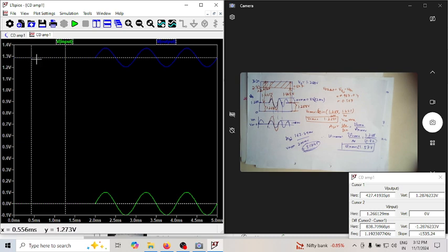Now when you're not applying any signal, it is 1.288 volts, that is DC voltage, VD. And let us see what is the gain of the amplifier. Once you apply the signal, you can see the signal is 100 millivolt top and 100 millivolt down. That is, this is peak to peak 200 millivolt.